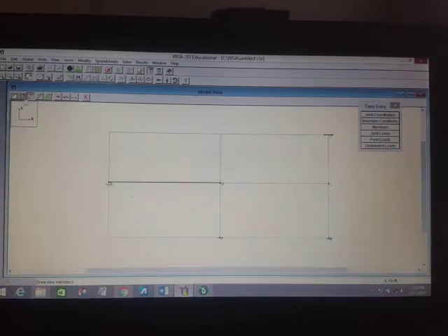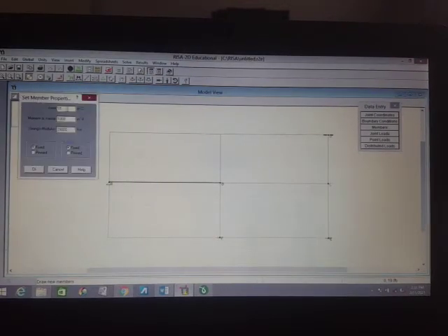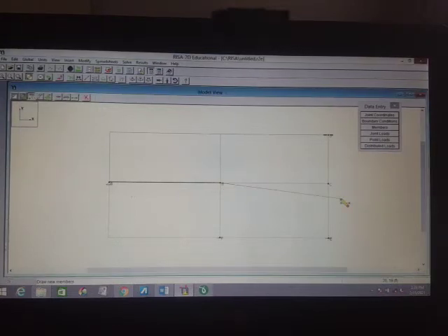okay, so we'll click this again. We have an area of 10 inches squared. So 10 inches squared, and then the moment of inertia is just I, which is 500. Okay, so the B is fixed, fixed. I mean the member B end is fixed, is this one.